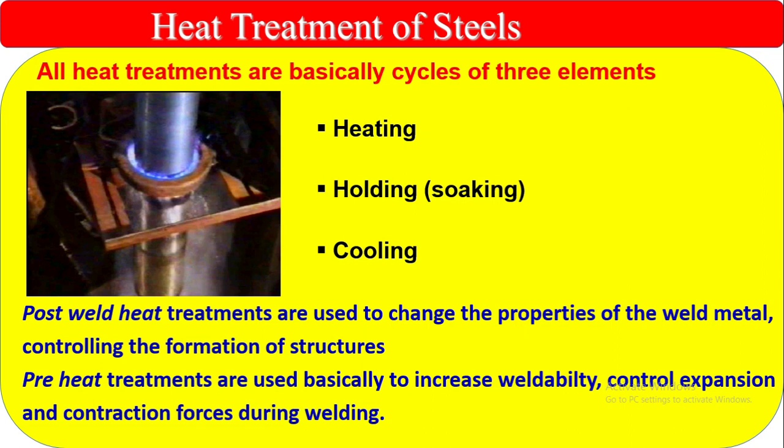Now the preheat treatment is usually done basically to increase the weldability. Preheat treatment and post-weld heat treatment are different. The preheat is done before the welding. Preheat treatment is used to increase the weldability and control expansion and contraction forces during welding.